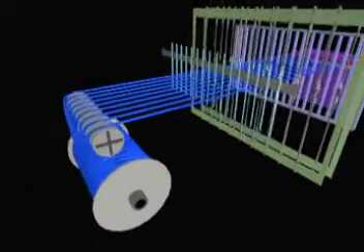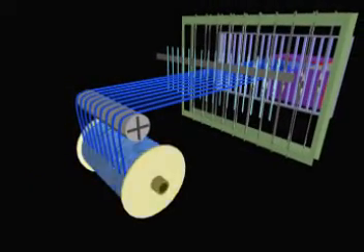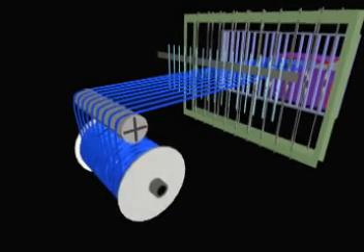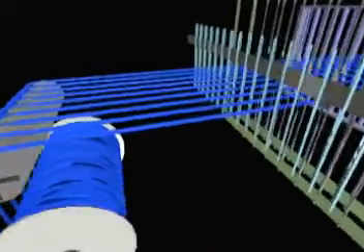The weaving process starts with the sized yarn coming off the loom beam in a single sheet or layer of yarn. The yarn then proceeds over a tension or whip roll that is designed to maintain a constant level of tension on the warp yarns throughout the entire weaving cycle.